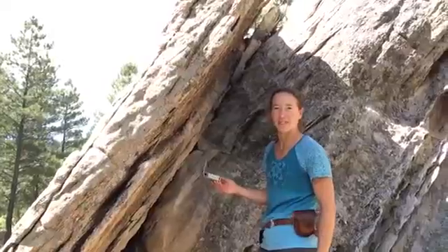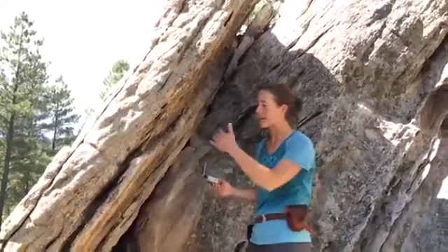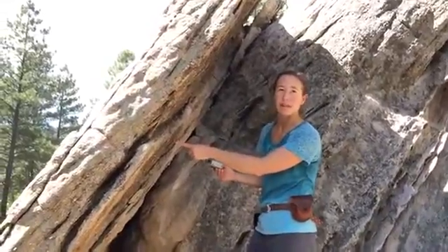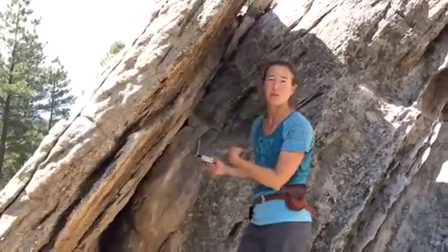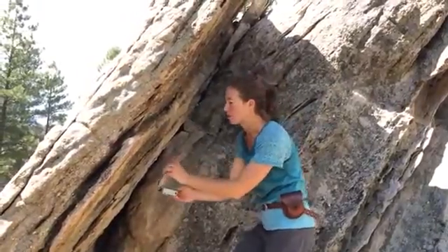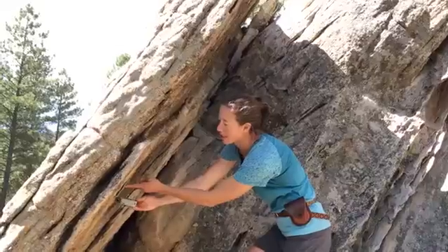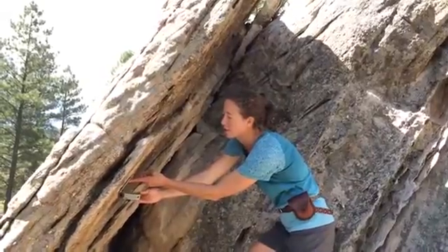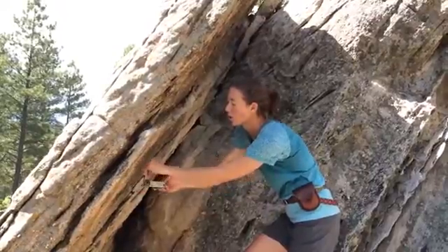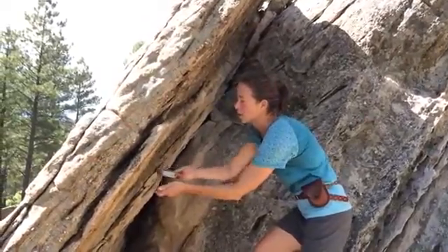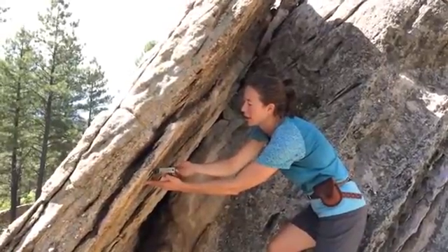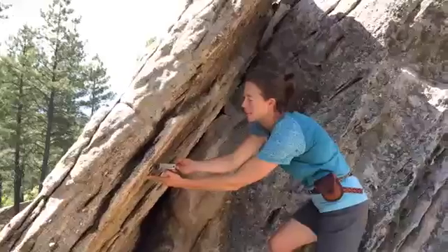With overhanging surfaces, it's important to visualize the plane being measured. In this case, the plane dips away from me, even though this surface is facing towards me. So to measure the strike and dip of this overhanging surface, I could use standard lid configuration, or I could use alternate lid configuration and end up with the same strike and dip.